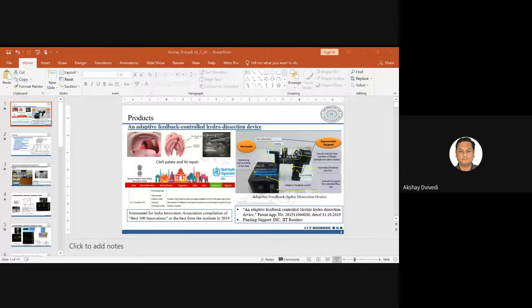So maybe if there is a channel that has to be created, wherein the width of this particular channel is 100 micrometer, and the depth is, let's say, desired as 70 micrometer, the conventional machining doesn't help here. Now, in case somebody says, okay, I do not want this channel to have a straight wall, in fact, we need some kind of a taper, and that taper is, let's say, 2 degree per micrometer. In that case, again, conventional machining cannot do that part. So for those scenarios, unconventional machining comes into existence.